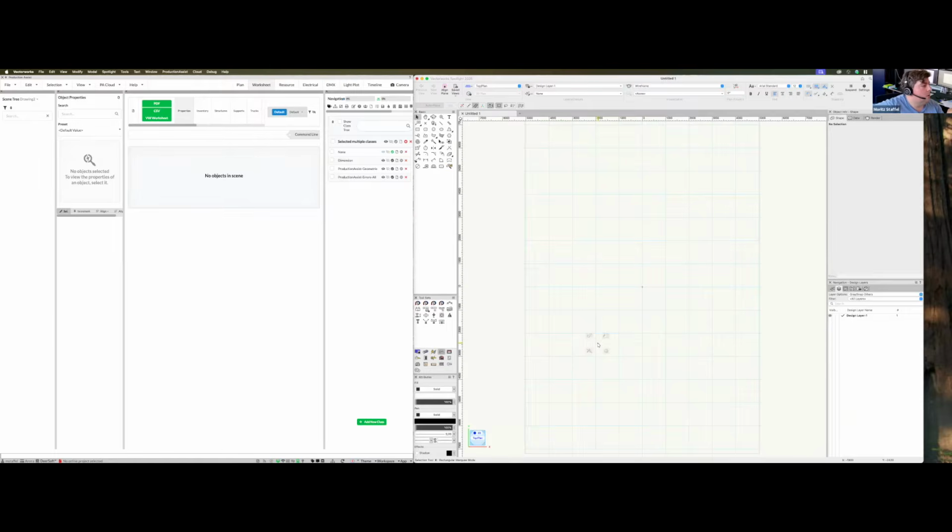One thing you need to know about Vectorworks is that it requires you to really work in details. The snapping in Vectorworks is good, but it's really easy to snap to something that you didn't intend to. And in order for us to calculate everything, we need the drawing to be accurate. So we need to make sure that it stays in the place where it should be and not 5 millimeters away, because when you have larger drawings, this will easily cause problems.